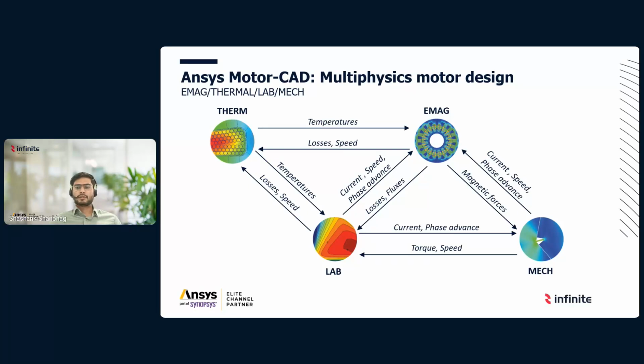In the thermal model, we can see how you can use different cooling methods available for the machine, check temperatures between interfaces of the machine, and the heat transfer across air gaps as it's strongly speed and temperature dependent. There is also the mechanical module in Motor-CAD where you can check magnetic forces and current data as inputs, and it provides the NVH analysis and gives us an idea whether the speed is mechanically achievable or not.